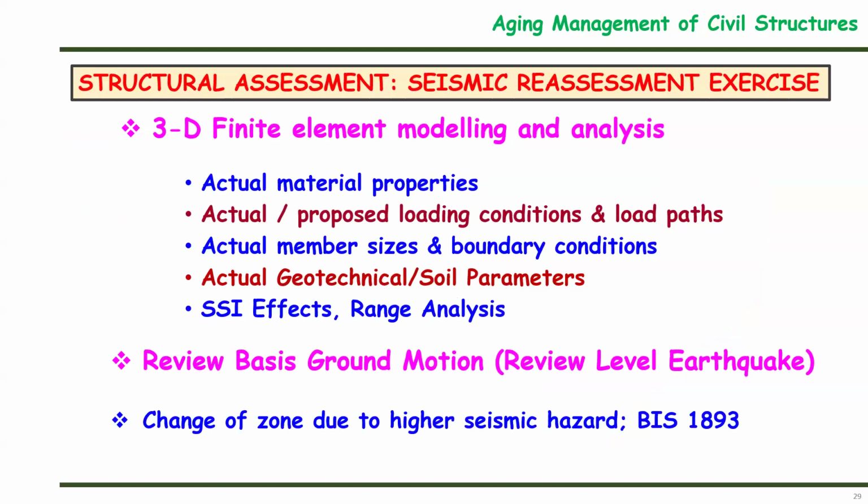Actually, if you look at the as-built drawing or the design basis report, some grade of concrete is mentioned. Here, actual material property means we are carrying out partially destructive tests to find out the compressive strength of the in situ concrete. Okay. Then, actual or proposed loading conditions and load path.